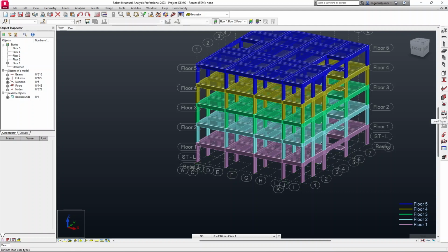So move on to the load definitions, the load types module. This one allows us to just define loads first of all. Then, as you can see, there's another one at the bottom. After defining those loads, we want to specify the values of those loads. So it goes to the load definition. For example, we have a live load. The first thing, the type is a live load, and then we define the value. The next step, we put it to be part of a code combination.